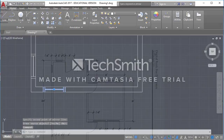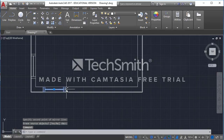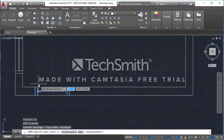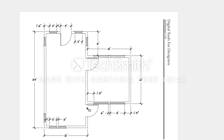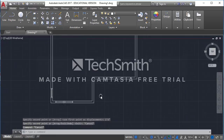If we look at our PDF, I believe the next window has a 6-inch gap in between. Okay, so if we know our window is 2 feet wide, and we know there's a 6-inch gap, I'm going to use my copy command. CO is copy. I'll hit enter, and I'm simply going to drag my window over 2 feet 6 inches and hit enter. This looks a little bit different than what's on the PDF because in the PDF they don't give the thickness of the window, but that's fine, that looks okay.